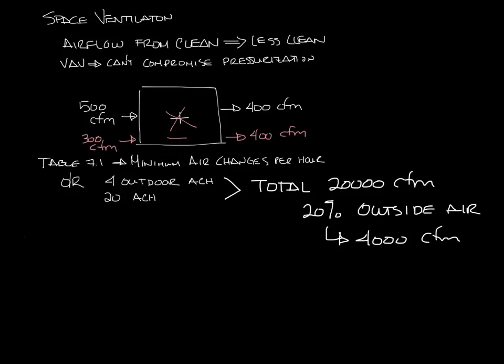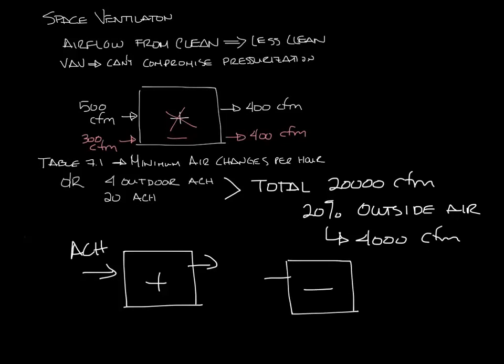So one more thing about air changes. If the space is supposed to be positively pressurized, the air changes are measured by what's supplied to the space. And if the space is supposed to be negatively pressurized, it's measured by what is exhausted from the space.